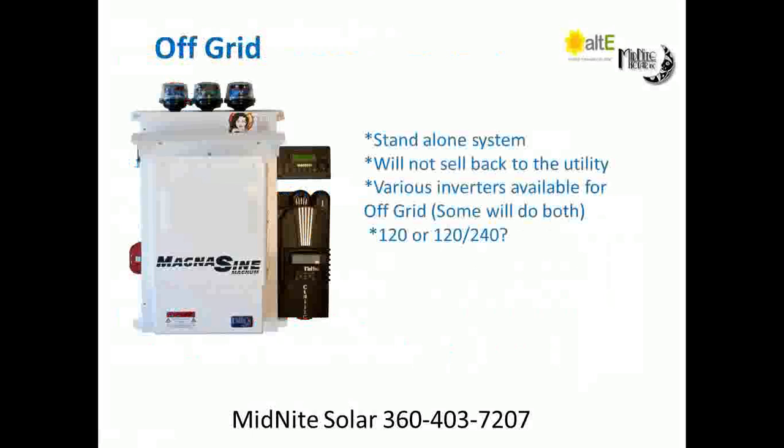So off-grid, basically, like I said, what off-grid is, it's a standalone system. It cannot sell back to the utility. Now, it can be utility interactive, so those can be a little confusing. Say you have the utility there, but you don't really want to use it, and you want to put a battery-based system in and be off-grid. Then you could do an off-grid system, and it will use the grid to charge batteries if need to, but what we call an off-grid inverter will not physically sell backwards to the grid or spin the meter backwards. Like I say, there are some inverters that do both, but as an off-grid inverter, it'll be a standalone system, will not sell back to the utility.